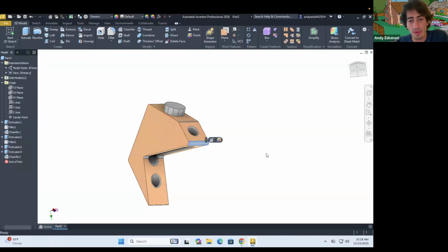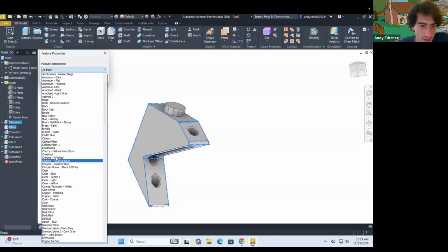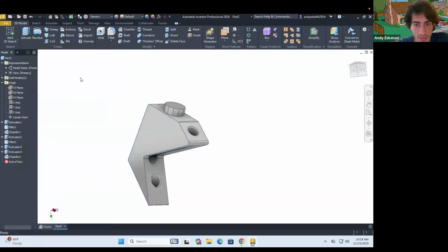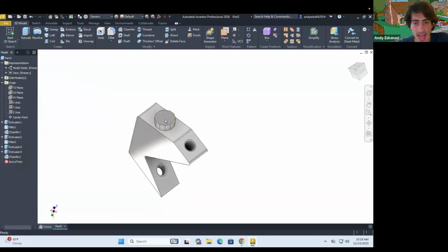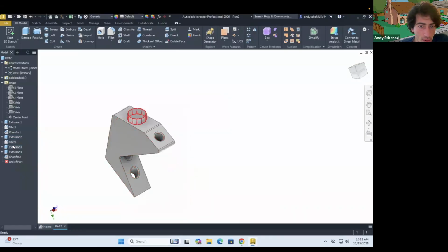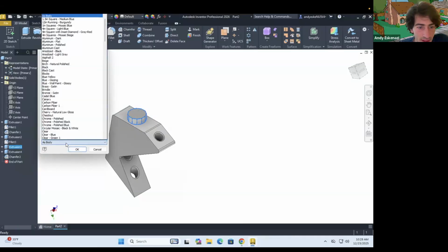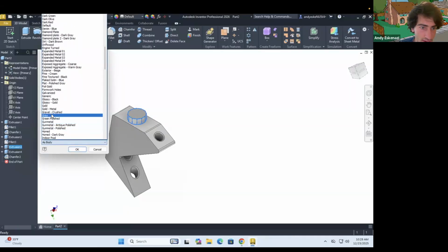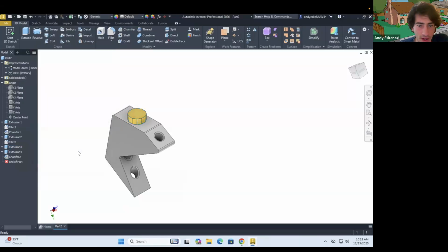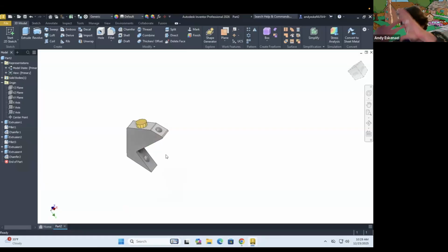Then if I wanted to also change those extrusions, I could say, all right, let me do Control Z. I wanted those two. So I go here to properties. I'm gonna make it chrome polished, so those two change. But that is still, it's difficult to tell, but these are different grays. For instance, I can go to extrusion free, properties. Let's make that gold, glossy gold. That's fine. See how it's actually changed the colors. So this is a way that you can change things on an overall feature.